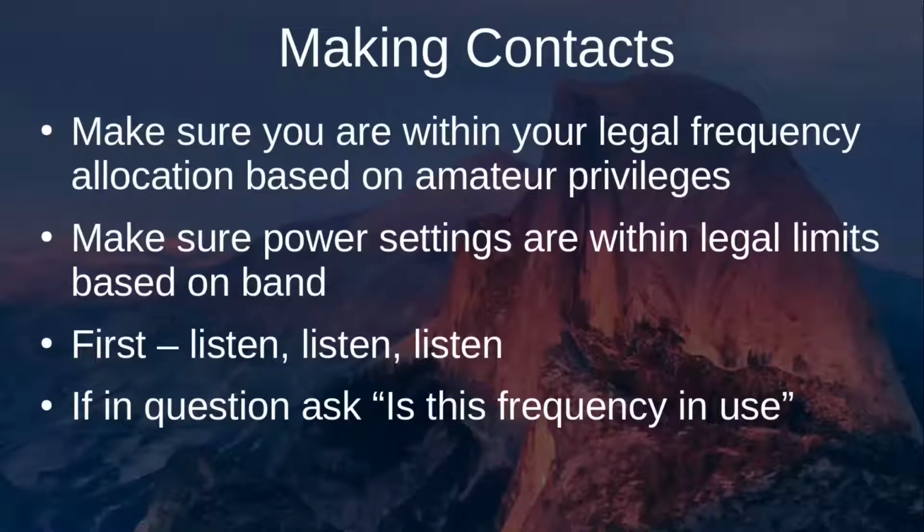And the first thing you do when you want to make a contact on HF or VHF or UHF is tune to the frequency and just wait. Listen, listen, listen. So first, listen if there's any other traffic on that frequency. The frequency could be in use. There could be two hams having a conversation back and forth. One may have stepped aside for some reason, and they're just waiting for him or her to come back. And just listen, especially with HF.